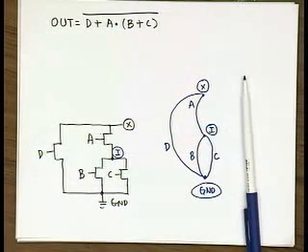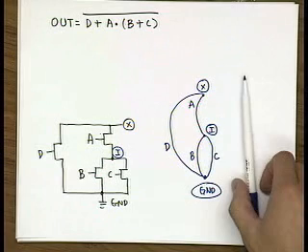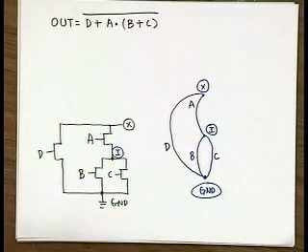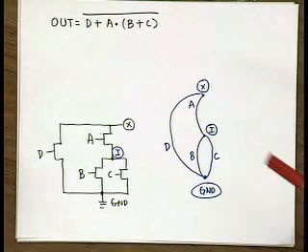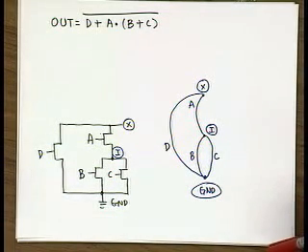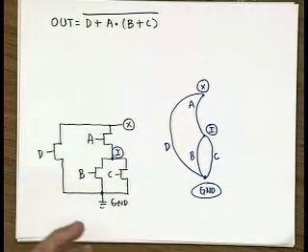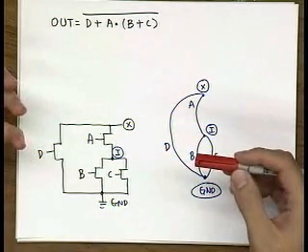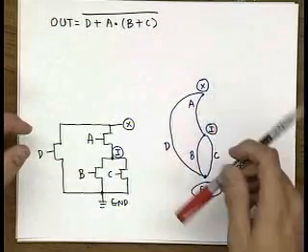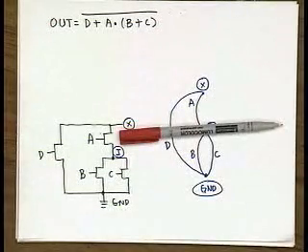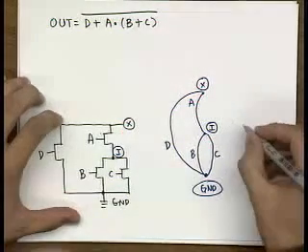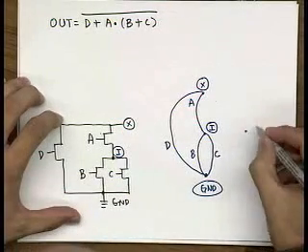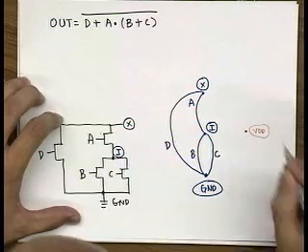So now, in order to construct the pull-up network, here's what I need to do. I know that my pull-up network basically connects VDD and X, because my pull-up network is responsible for providing all the logic 1s at this X. So I'm going to put a pull-up network on top of this network, but now instead of going vertical, I'm going to do a horizontal direction pull-up network. And then I can basically identify nodes VDD and X.